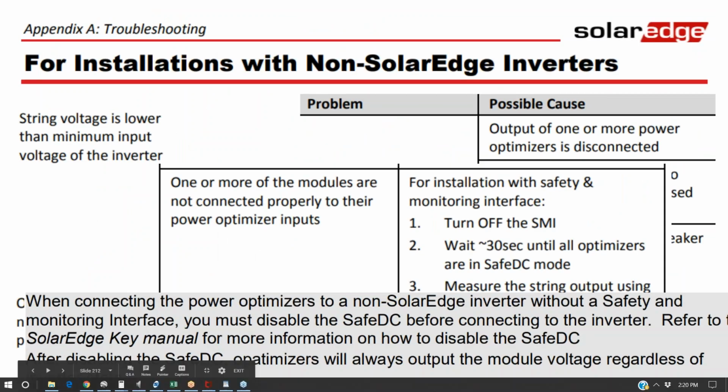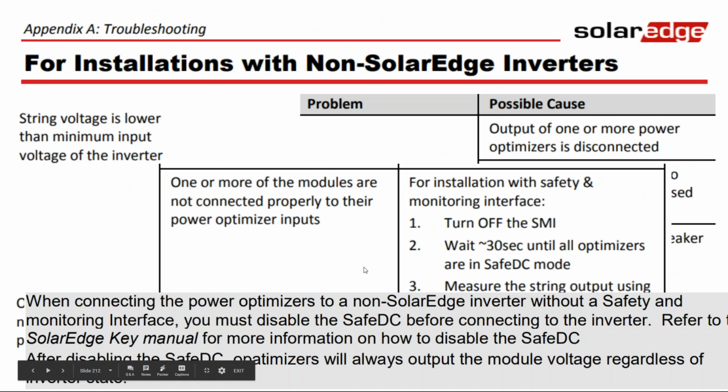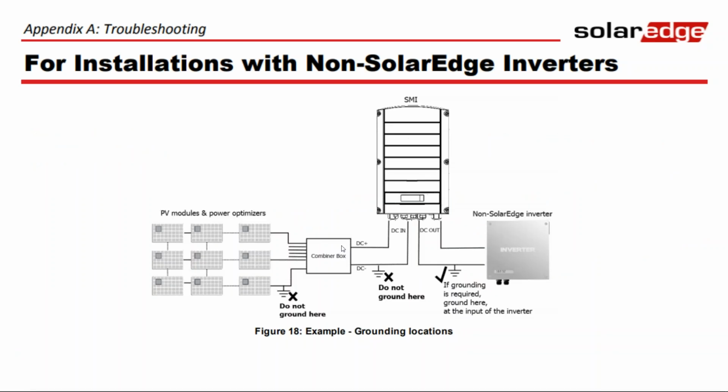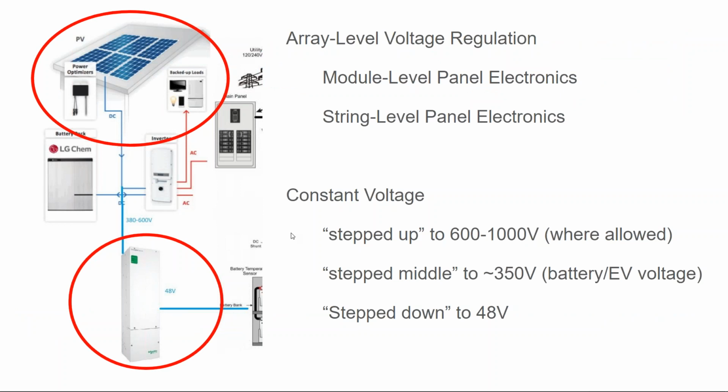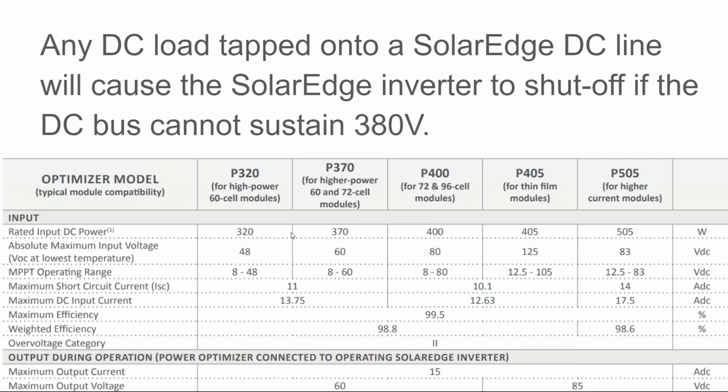What you want to avoid is having two master inverters trying to drive the system, but then again, your lead acid battery inverter can be the master with your lithium ion enabling the demand management mode of the lithium ion inverter. The concept of that is called an energy server, and that's more of a commercial thing that we explore further in our commercial demand management class. So I'm just going to quickly get through the rest of these slides.